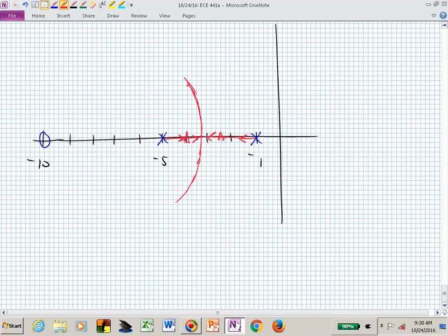And so now if I drew this at minus 10, I would be up at 7, plus and minus j, a little bit less than plus and minus j7. And then where am I going to re-enter? I'm going to re-enter at that radial distance to the left of minus 10, my real line. So if I cranked up the gain k enough, I'm going to come back and have real roots again. And if I keep cranking it up, those are going to meet to the left of minus 10 at about minus 17. One's going to zip off to minus 10. The other one's going to zip off to minus infinity. And that will be my root locus diagram.